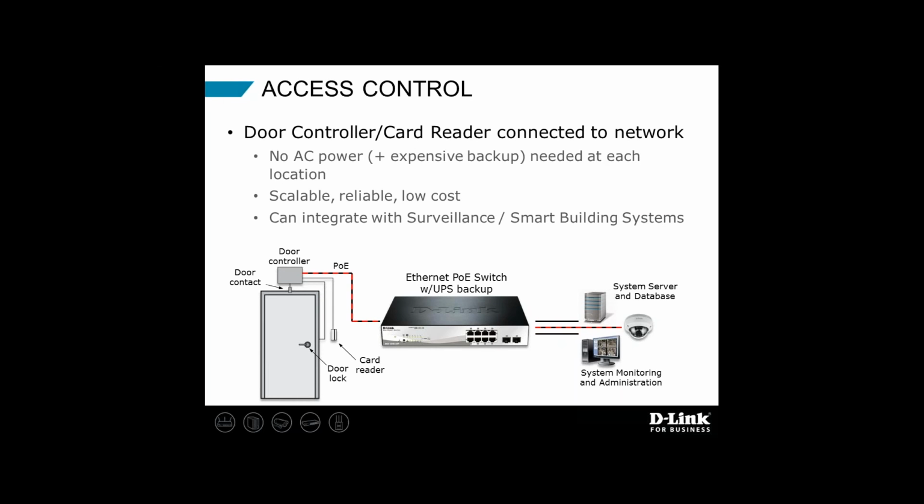Here's one, access control. Quite often you've got door controllers or badge readers or card readers that can be PoE powered, and there are a lot of benefits to doing that. If I don't have PoE powered door controllers, then I've got to get AC power out near that door, and I need probably pretty expensive AC power backup. In the event of a power failure, I still want to be able to operate that door. That can cost a lot of money.